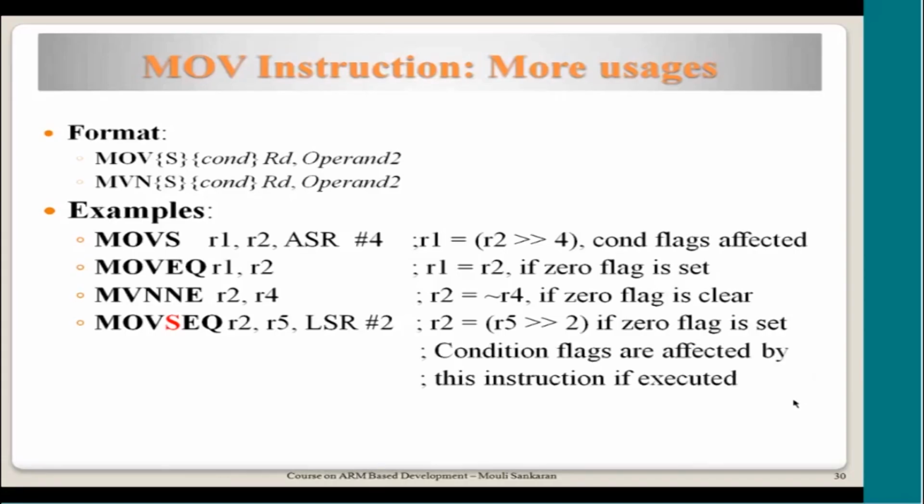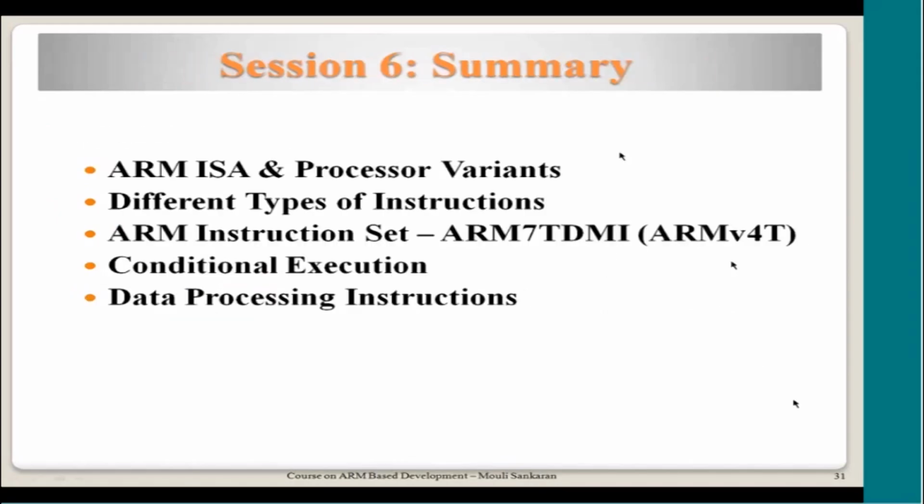Okay. So with this, we are coming to the end of this session, and we covered these following features: conditional execution, and MOV and MOVNE in particular. I want you people to try out these instructions and understand them fully, so that when some more complex instructions are introduced, you are already familiar with this and you will be able to understand them better. So spending a lot of time with the simulator is a must, and I tell you, once you start understanding what is happening at the register level and the flags, you will start enjoying writing more and more assembly.